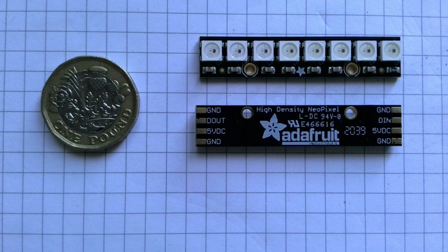There's one there, it's 8 NeoPixels on a board. The decoupling capacitors have been added. The input snubbing resistor has been added. The whole circuit's there. It's been built. It's been tested. So it's dead easy for me to use that to check out a NeoPixel circuit before I start plugging it into the NeoPixel circuit that's on the layout or that's on the board that I'm working with. That's a great way of checking out the NeoPixels.